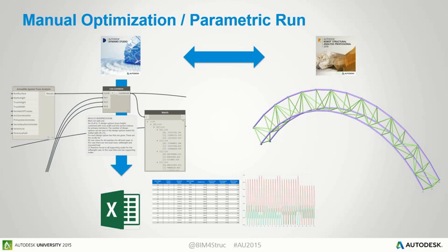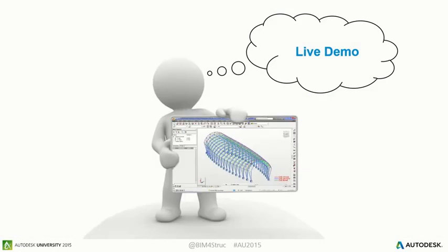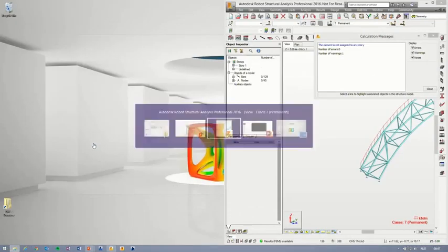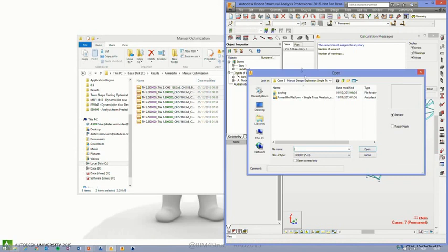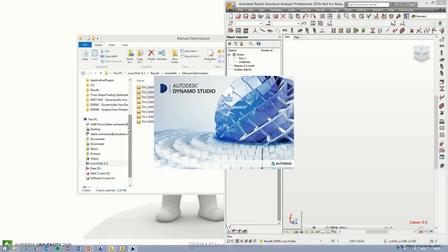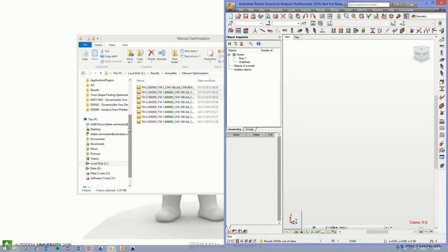You don't want to have a structure with 20 different section types. You want to generalize a little bit, otherwise the contractor has too much work to do, okay? So therefore, you'll see it's a very low value, it's 50. So which would mean if we have those 10 members again, weight is 500 kilograms, there are 2 members which are over-designed, then I would have 500 plus 2 times 50, which is 600. Okay? So this is what the script will do.